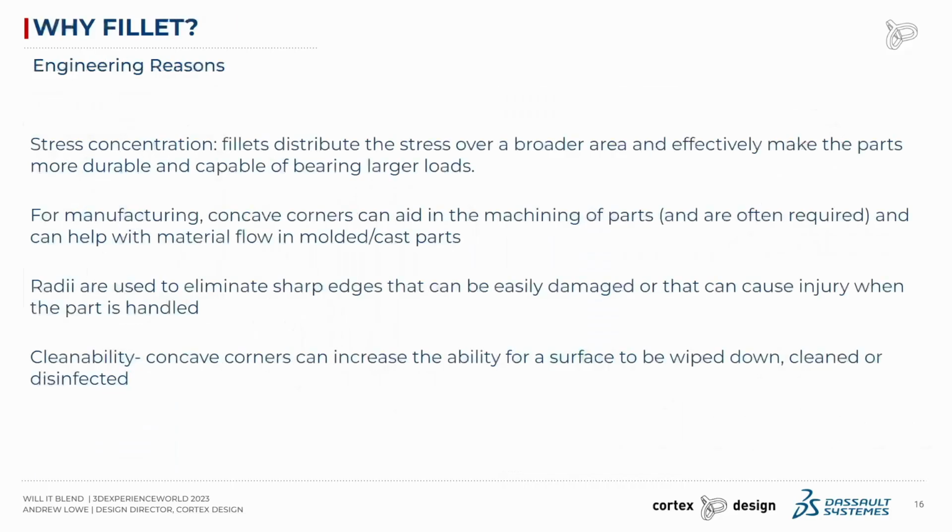There's also engineering reasons why we'd add fillets to the models. Fillets can reduce stress concentration. They distribute loads over a broader area. They make parts more durable.